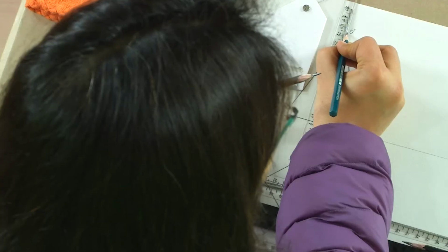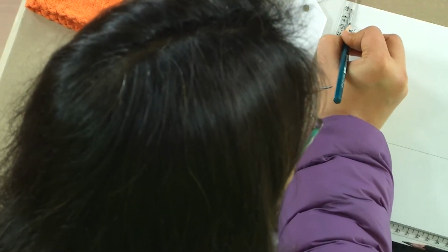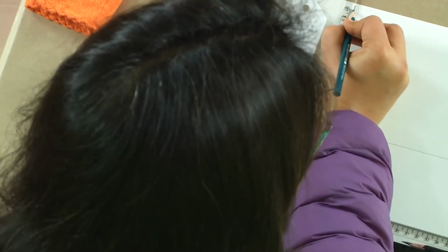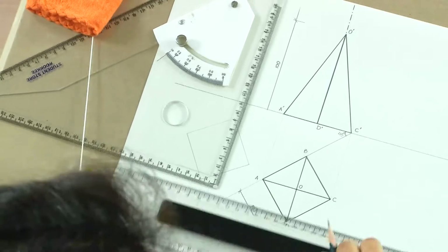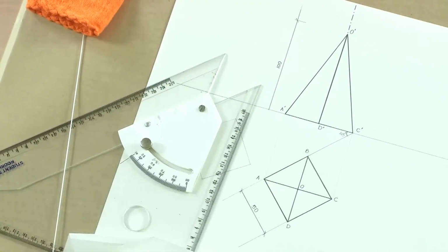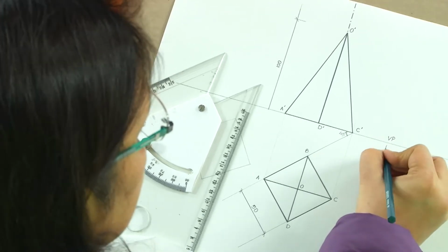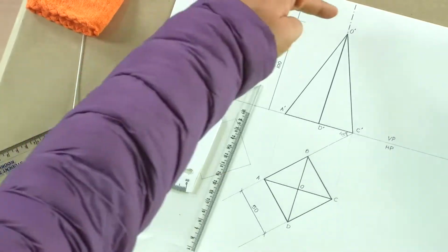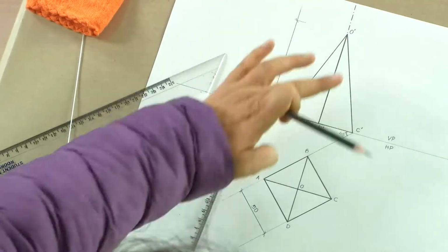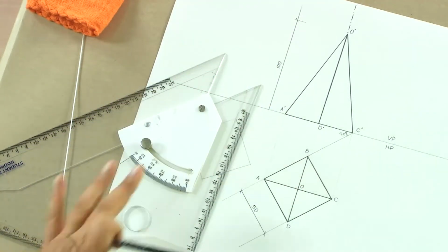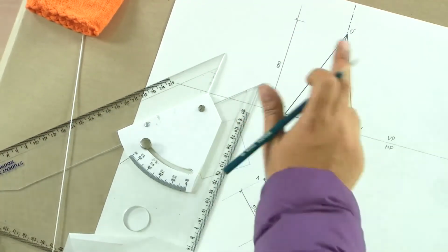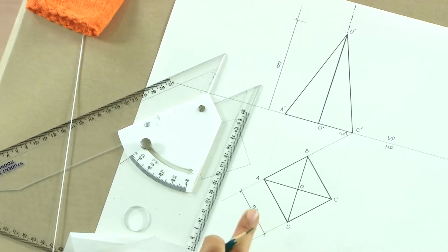That's the condition. Now, one thing which is left for us to draw is the extension of the axis line. The axis is going to be seen like this, since we will not be seeing the axis anywhere but in the front elevation in VP. This is VP here and this is HP. So, what you see here is this axis which is perpendicular to HP and parallel to VP, which is why we see the true height in VP and the true dimension of the base in HP. So, this is one of the conditions which we have.